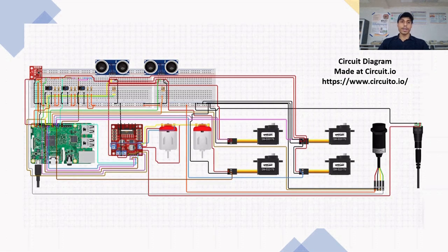Now let's see the circuit diagram of our project. You can clearly see all the components that are connected to the central controller, which is the Raspberry Pi. The Raspberry Pi is connected to the motor driver, which in turn is connected to the electric motors. Ultrasonic sensors are connected to the GPIO pins of the Raspberry Pi for data input, which are crucial for autonomous navigation and for the calculation of distances.